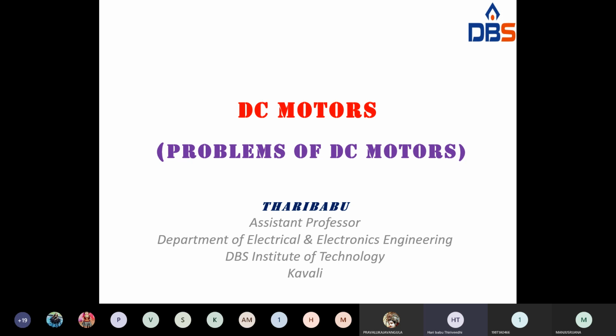That power loss is called eddy current loss. Eddy current loss is mainly proportional to the square of the frequency. Now, how can you reduce the eddy current losses? By using thin laminations. Totally, hysteresis losses plus eddy current losses is nothing but iron losses. How can you reduce the iron losses? By using silicon steel laminations.